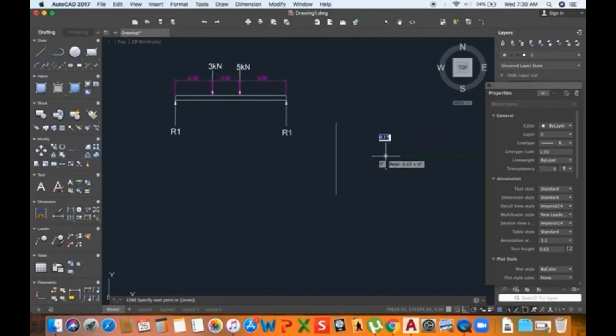It doesn't matter where, how far, but I normally like to keep it symmetrical, meaning right at the middle, somewhere at the middle. So I'm going to connect it to both ends, as well as all the points where the lines end. In this case, it's 1 additional point. If it was 3 forces, it would be 2 additional points. If it was only 1 force, then you would not need this line, since the line would start here and end here. So this is my pole diagram.